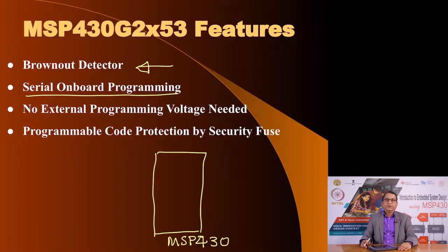You could utilize it. If you choose to use in-application programming, that is programming with the bootloader, then it uses the UART which MSP430 has. And in fact, our MSP430 evaluation kit, which is the MSP430 lunchbox, uses this method. This allows you to program microcontrollers with very little external support, and we will show you a variety of ways of actually making your own evaluation kit in case you do not have access to the lunchbox. We will show you how you can create your own setup.